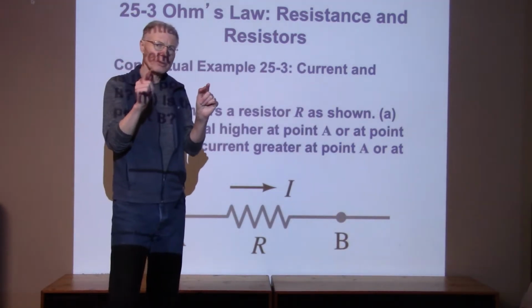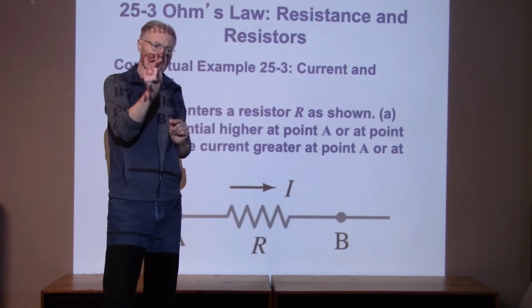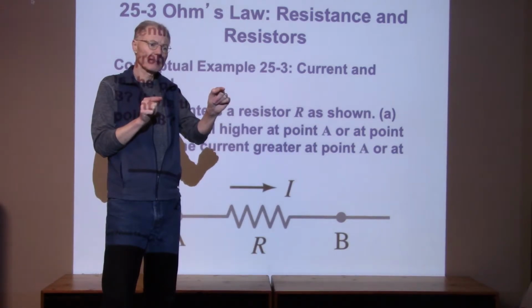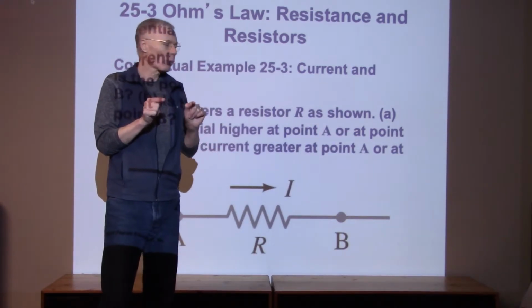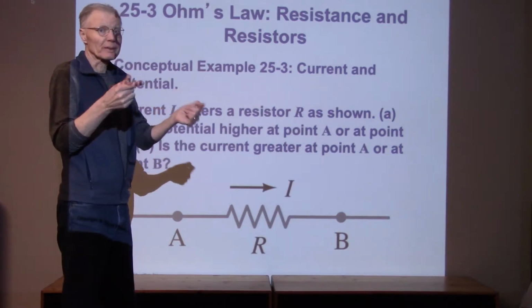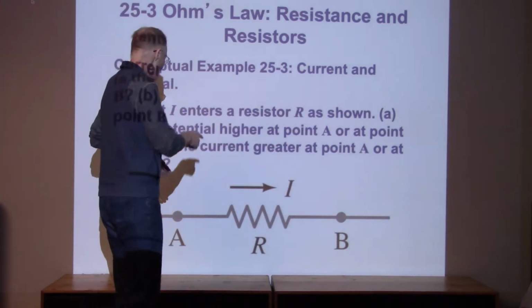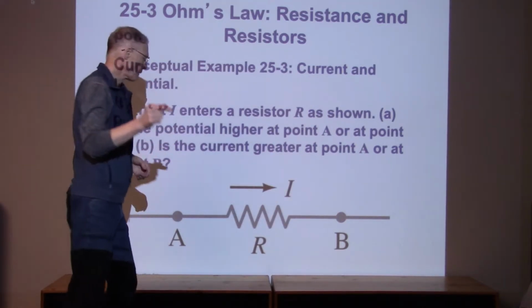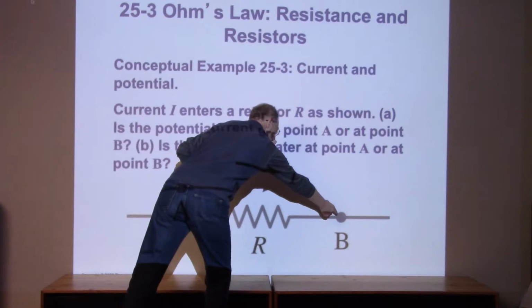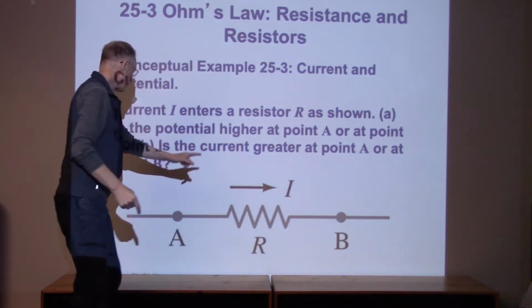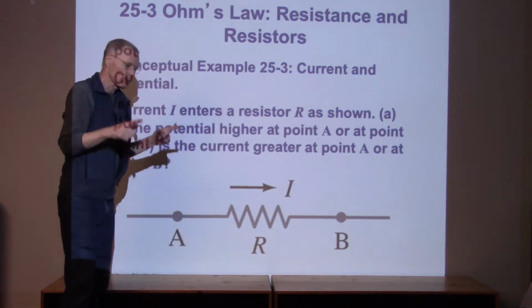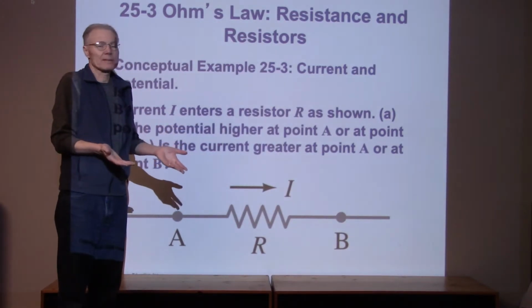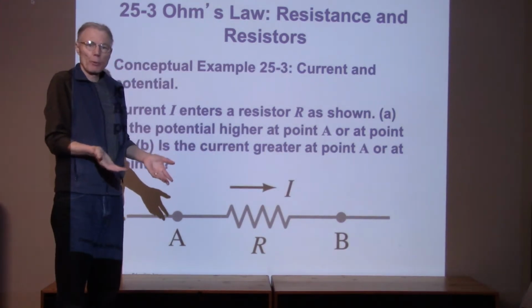Now remember, on the voltmeters that we looked at in lab, one of the contacts on the voltmeter said common, and the other one was the variable voltage. So the way we would measure this is, for example, we could hook this up a couple different ways. Since A is at the higher voltage, if I take the common connection on my voltmeter and place it at point B, and then I take my variable volt line and place it here, my voltmeter will read a positive value. So, positive whatever, positive 3.7 volts.